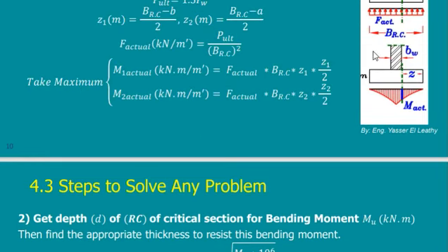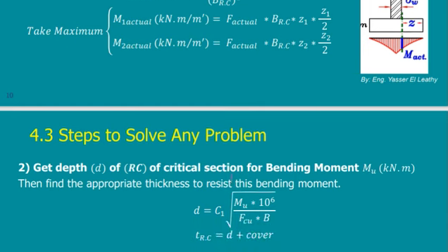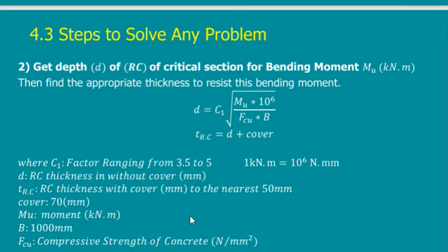Once I get the moment, then I need to calculate the depth. There is an equation, it is given here. You can use your equation. If in reinforced concrete design you have another equation, use it. This is the one I am presenting, but if in design of reinforced concrete sections you have another equation for getting the depth of the section,